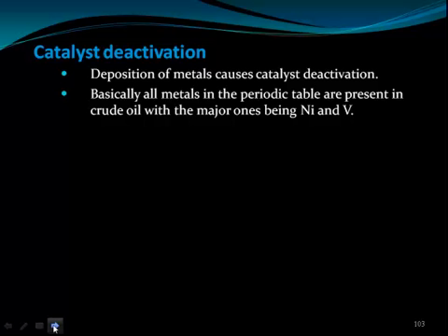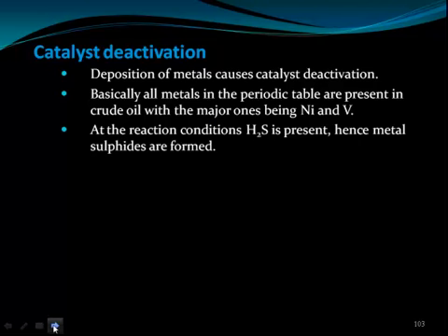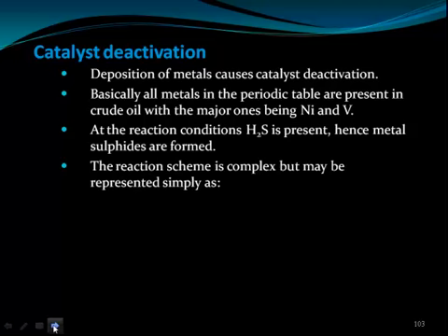So deposition of metals causes catalyst deactivation. Basically all metals in the periodic table are present in the crude oil, with the major ones being nickel and vanadium. At the reaction conditions, hydrogen sulfide is present and metal sulfides are formed.